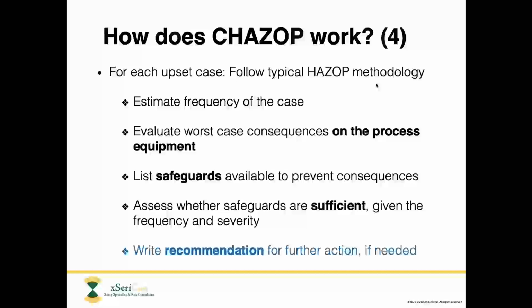We would not want to embark on trying to perform such an assessment in detail during the CHAZOP because it's too specialized and requires a different type of methodology. So really all I recommend in CHAZOP is just to ask the question yes or no, has it been done? And if no, then why not? And is it necessary? And when will it be done? So that may end up raising a recommendation for further attention.